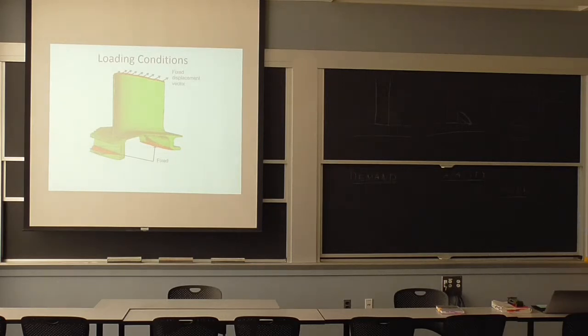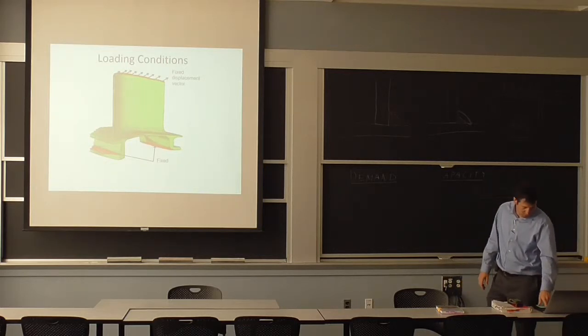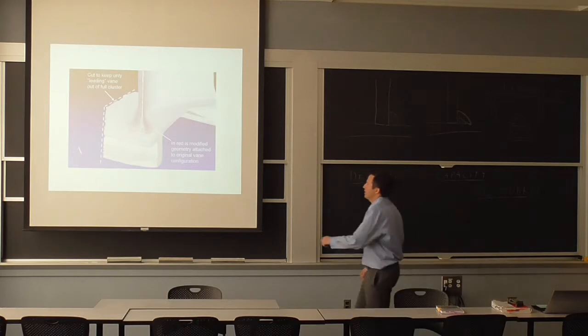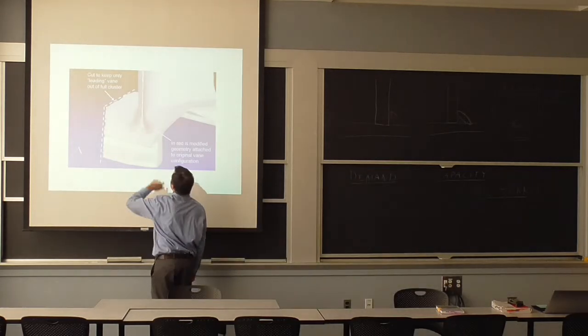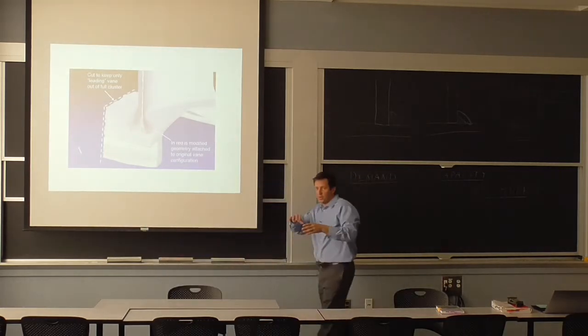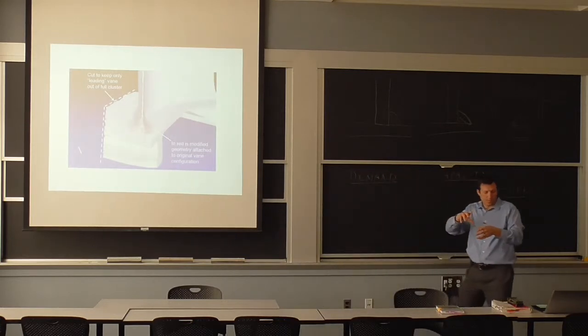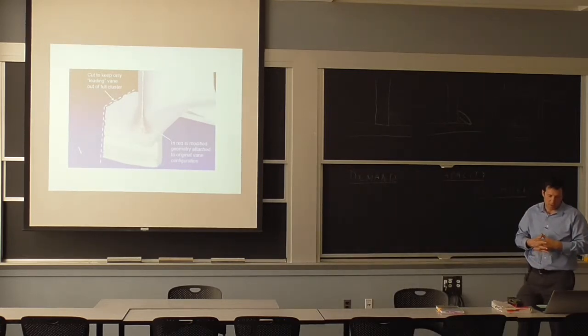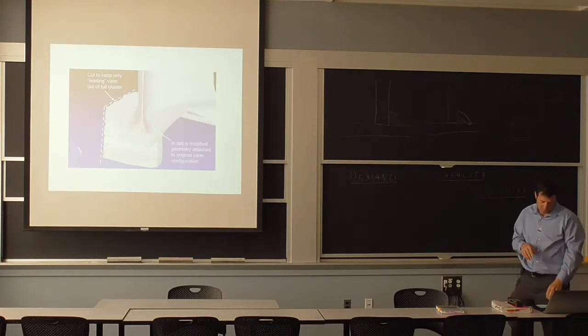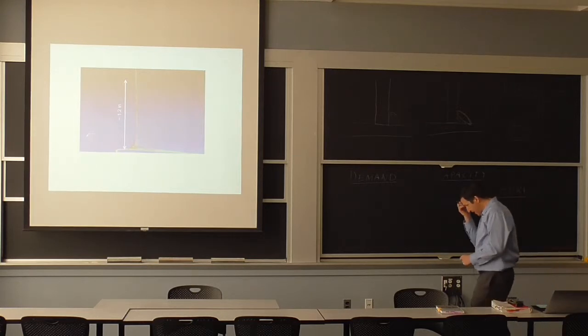That actually goes along with the analysis I'm showing, where we had it on the computer and we were interested to look at the stresses here at the very bottom. It's the leading edge. There is always a bending force, so just from bending with this radius is where you expect the higher stresses, and from the example you can also expect some impact and abrasion of the surface. So the idea actually was to see, can we make this stronger?